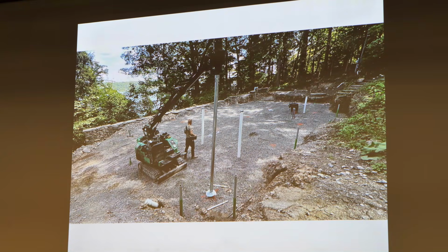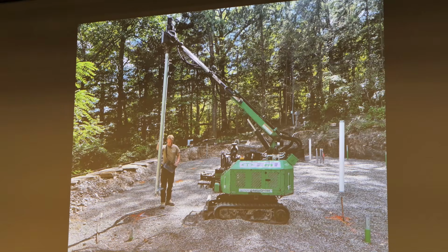This is from 2 weeks ago, where we're using helical piles to drive into the ground so we're not having to drop concrete, so we can lift up off of the ground and allow air to move around the entire house as opposed to dealing with the kind of water issues you get when you put something in on a hillside slope. One person, one machine, one helical pile in 2 days. At the end of life, this can be screwed back out.